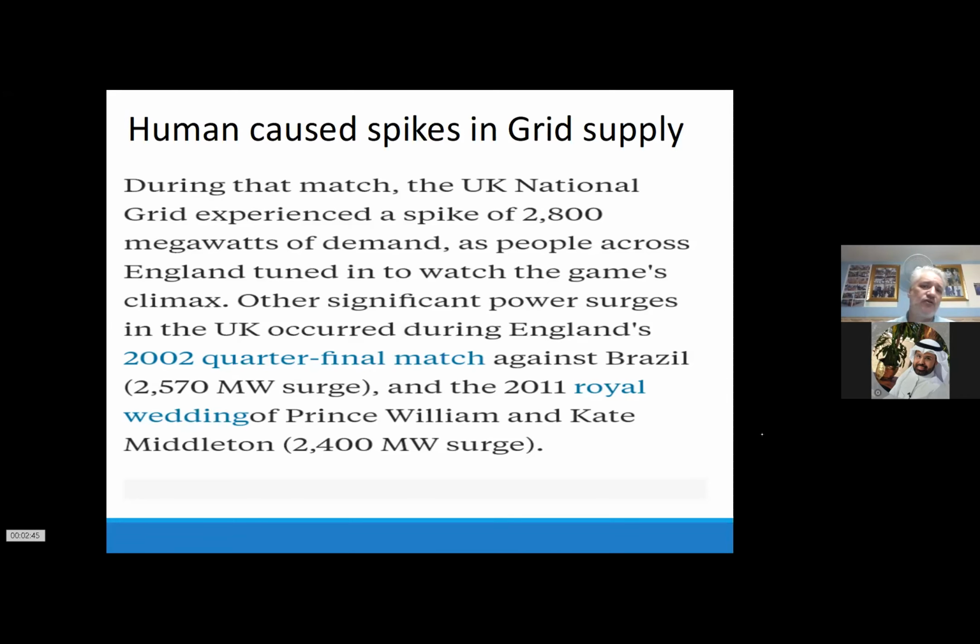So that means I can oversize this inverter. If I have 12 strings and normally I only put 10 strings into the inverter, I just put 12 strings in, because I know these strings will not perform the same as a 10-string inverter or even an 8-string inverter, because they are shaded. That means you make the 1.5 or 1.27 DC-AC ratio to overcome the problematic halfway 50 to 60% efficiency of some inverters. You will see otherwise always inverters running on 50, 60% load, while all the other inverters are on 100%.